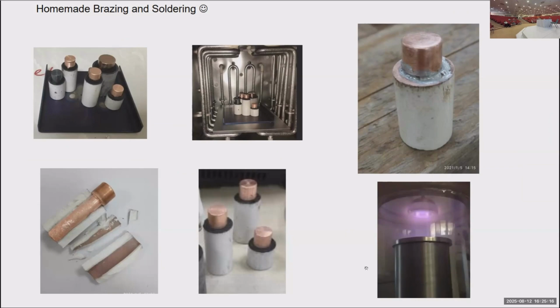The ceramics were broken due to some erratic calculation, because the copper was extremely expanded. And you have to make some geometries to escape such a problem. Those are the others. I have checked all of them with the helium detector.